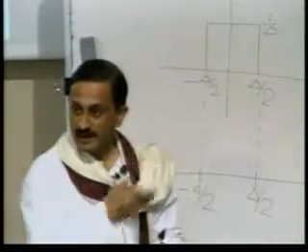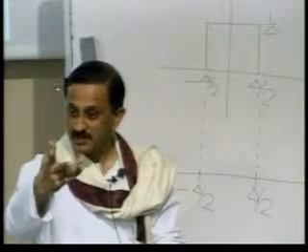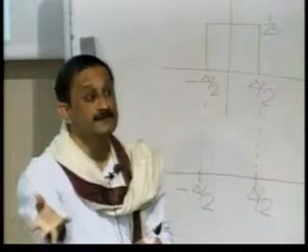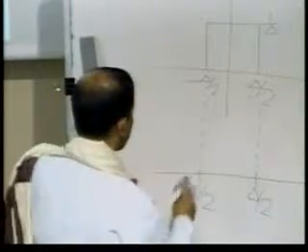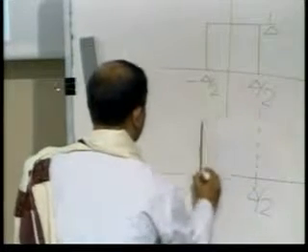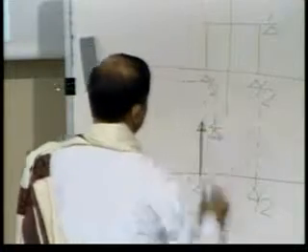If you take a running integral of the derivative, it should give you back the original function. So in the running integral, there must be an impulse which contributes an area of 1 by delta. So you must have here an impulse of 1 by delta in the derivative. A positive impulse of 1 by delta.